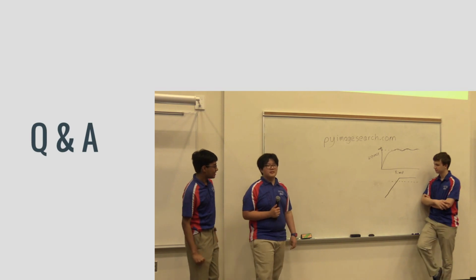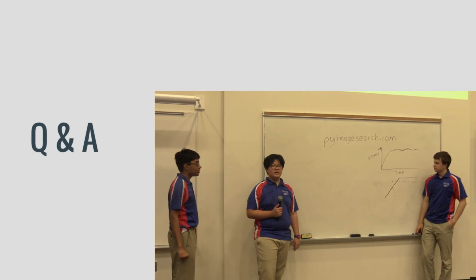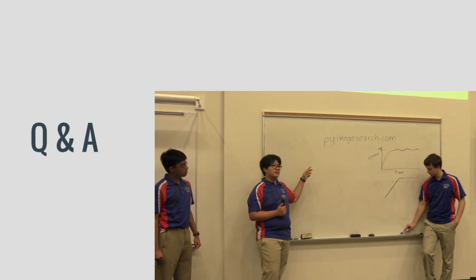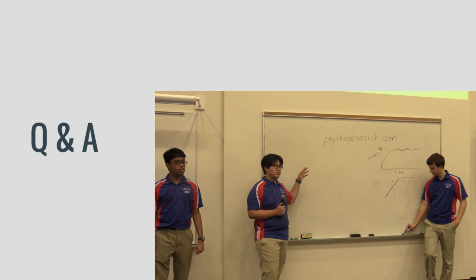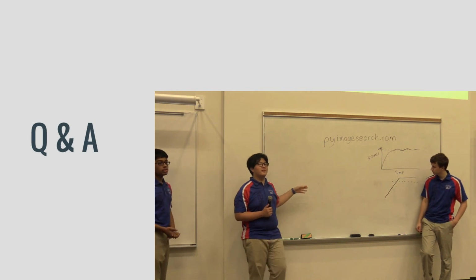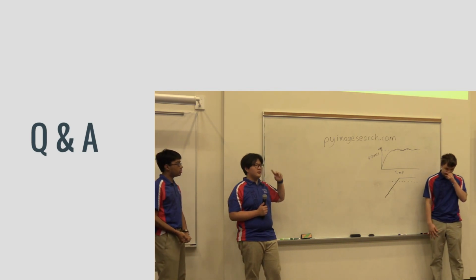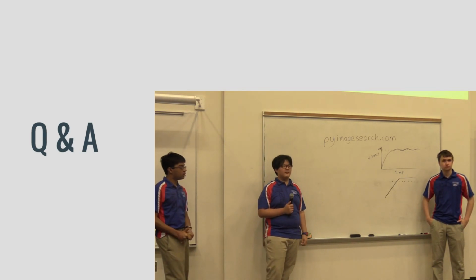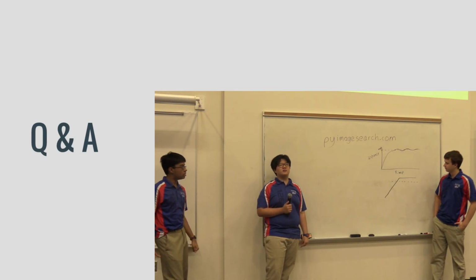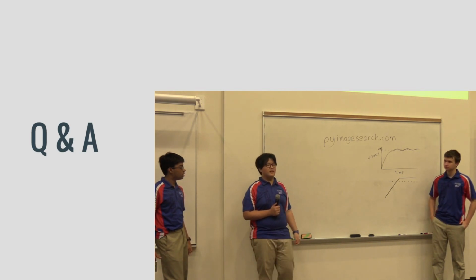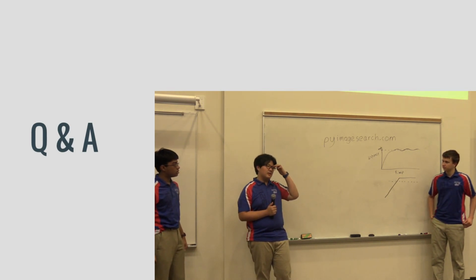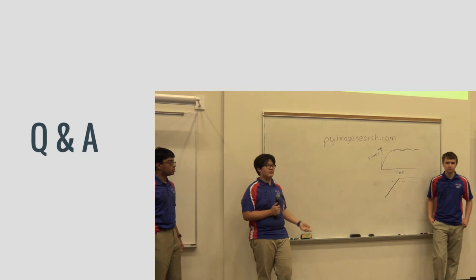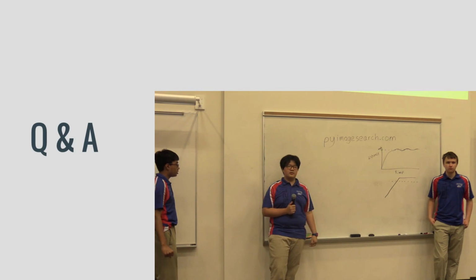Oh, okay. The first thing I would say is the demo we showed with the HSV thing. We use that to set our HSV values, and we try to do that fairly regularly because HSV is pretty stable and pretty nice at finding objects, but sometimes lighting conditions change and something might break. Maybe the LED burns out, so you have to switch it out, and the LED brightness isn't going to be exactly the same. So we try to tune our HSV values. That's our first step in tuning our vision processing.